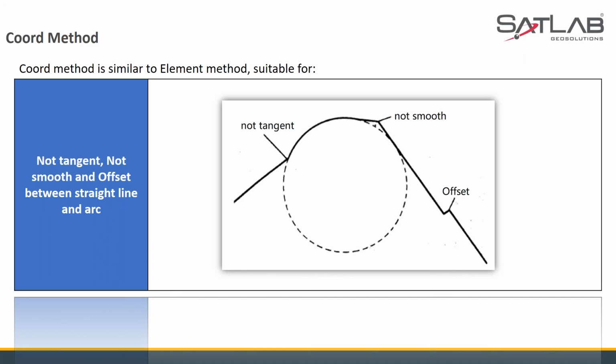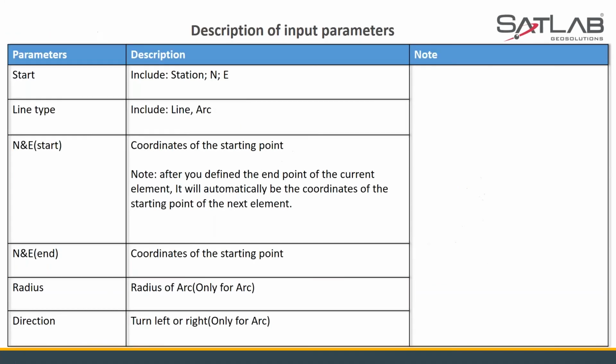Add another line. So you can add the different segments, and if you are going for the line, you have to give just a simple length of the line and the azimuth, and so on and so on. This is how you can see over here. So it's the same thing that I did in the previous one. I'm just saving the alignment. It's done.